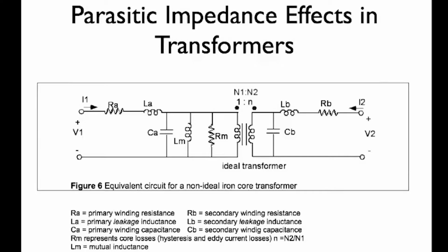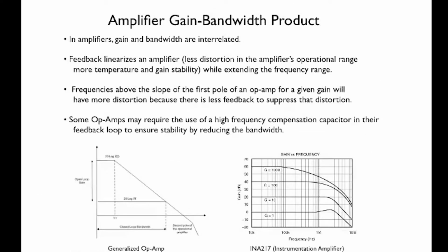One benefit is that we don't need to add capacitors to block DC, the 48-volt phantom power, from getting into the mic pre anymore, because the coil of the transformer does that for us. But I guess we also don't need to intentionally block RF either, because the parasitic capacitance of the transformer will act as a low-pass filter, assuming the transformer has been made well enough that it has a wide enough frequency response, the frequency response we want for our audio. Okay, next slide.